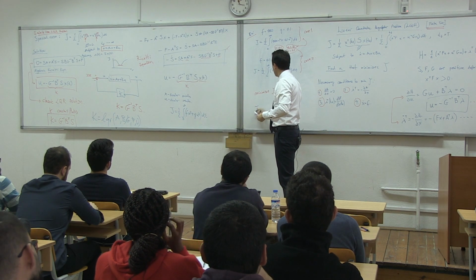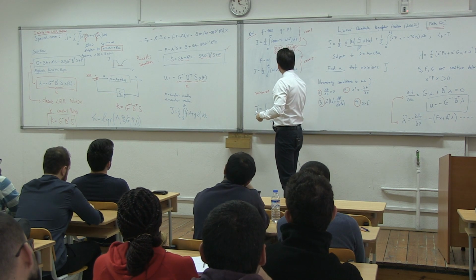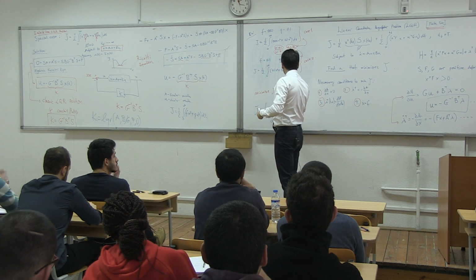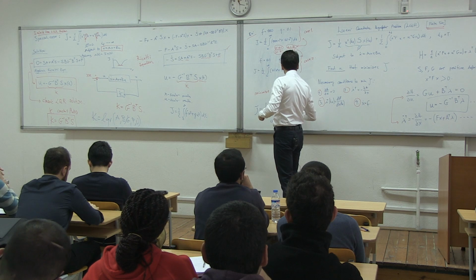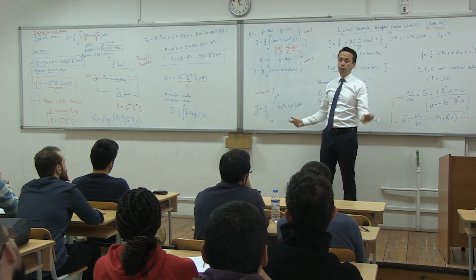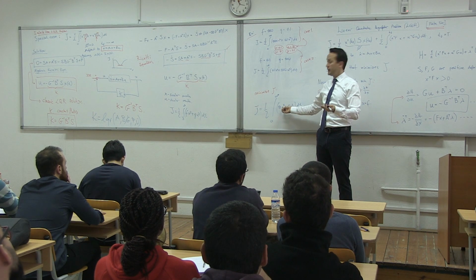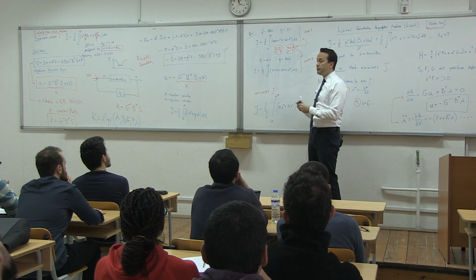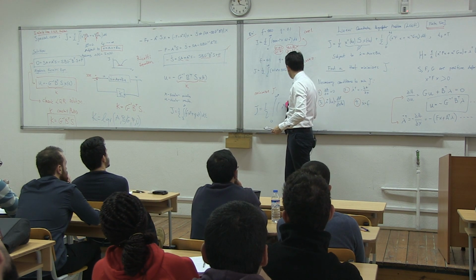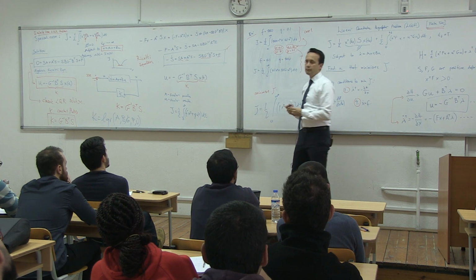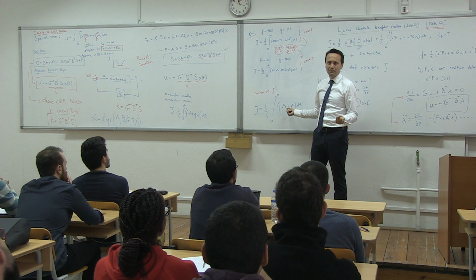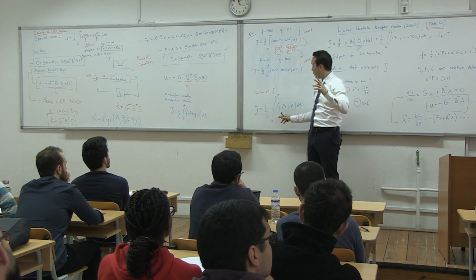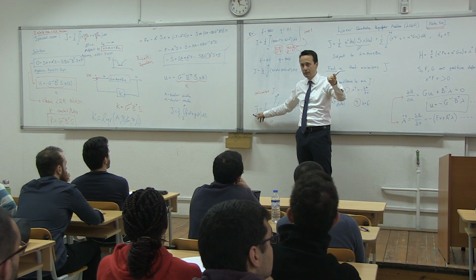Well, then you can just make it comparable. Then choose a j that looks like this: integral from 0 to infinity of, I don't know, 10x squared plus 10u squared dt. Now, both of them are 10. They are equal. So a movement in x will affect the minimization problem just like the 10 over here. So, well, if they're comparable, why not make them 1, 1? And for the optimization problem, it doesn't matter. It's trying to find the minimum j. You can make 1000, 1000. It will still try to find the combination of x and u that will minimize j.